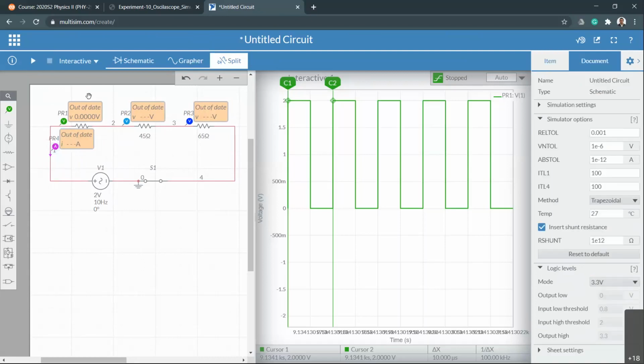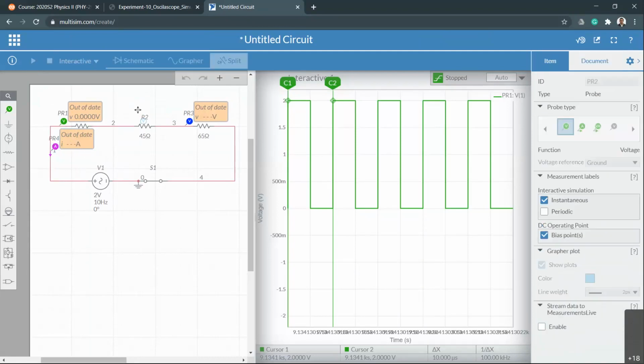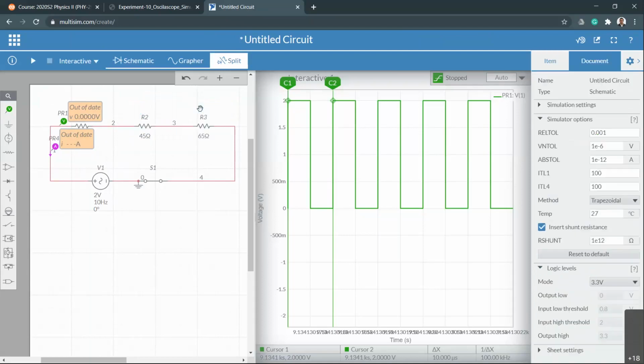And all you have to do then is click the run button. If you click that run, it will tell you the voltage across each resistor. You can actually use many voltage sensors or one voltage sensor. It doesn't matter. So let's use one first and then see whether I can change that accordingly and then measure voltages. Okay, let's use one voltage sensor and then measure across each of the resistors.